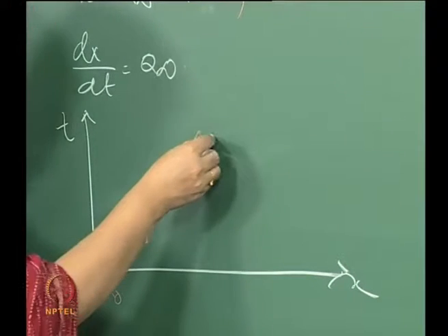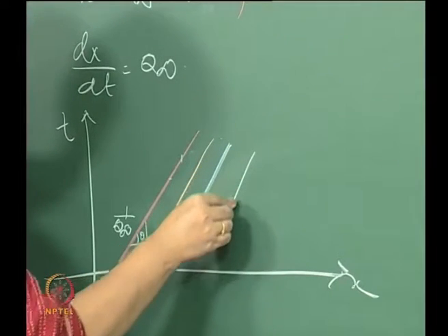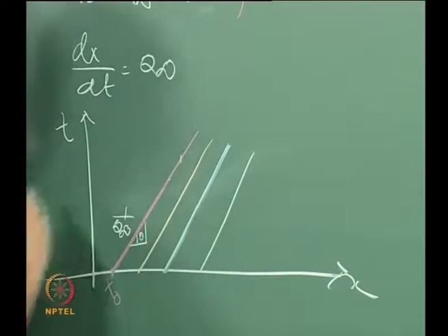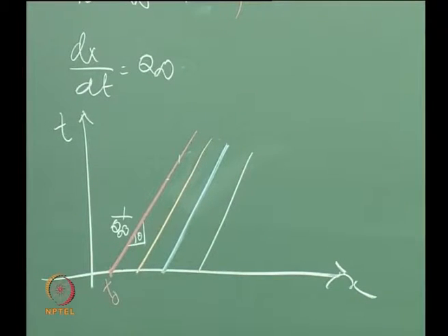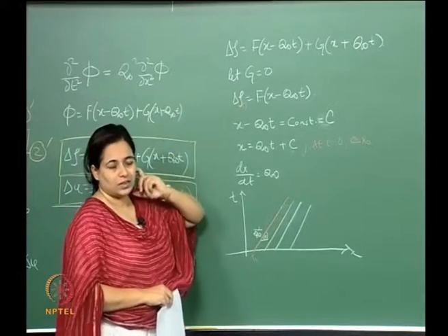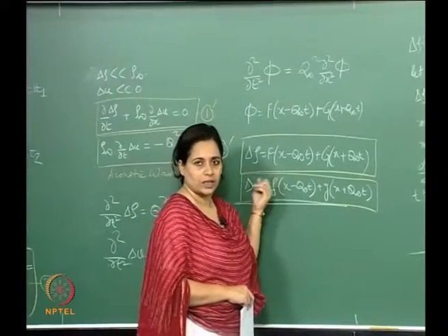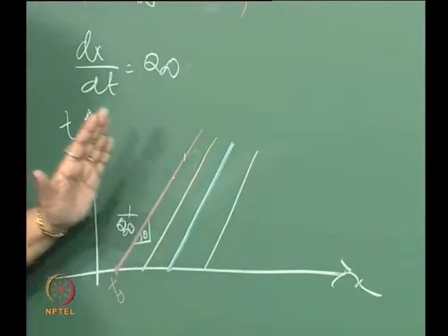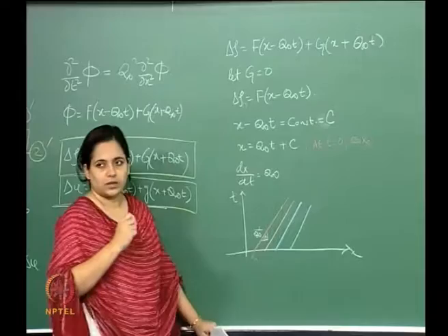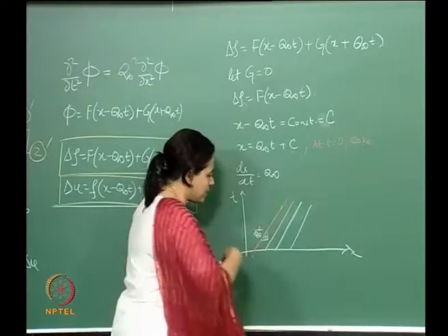Okay. So, then what we get over here is a series of lines, right, and the slope is the same. The slope is the same for all these lines, isn't it? It's just that this value is changing. Okay, that depends on this delta rho actually. So, what we see is that the solution that we got for the finite wave basically emerges into several straight lines, right, which means that on every line all the particles are traveling with the same velocity, isn't it, dx by dt. So, on every line here the velocity is the same.